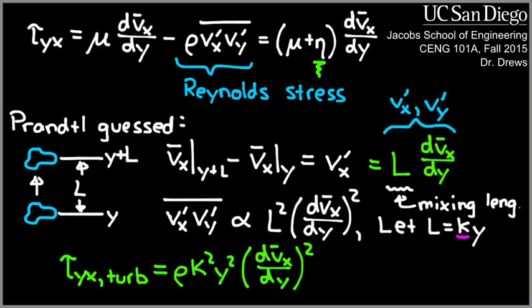squared. And when I am near the wall, this is an important approximation as well, we call this tau sub naught, which is a constant if you're at the wall. We'll see how that affects things in a minute. But at any rate, this is the expression that we're going to work with. And this is completely due to the mixing length hypothesis of Prandtl.